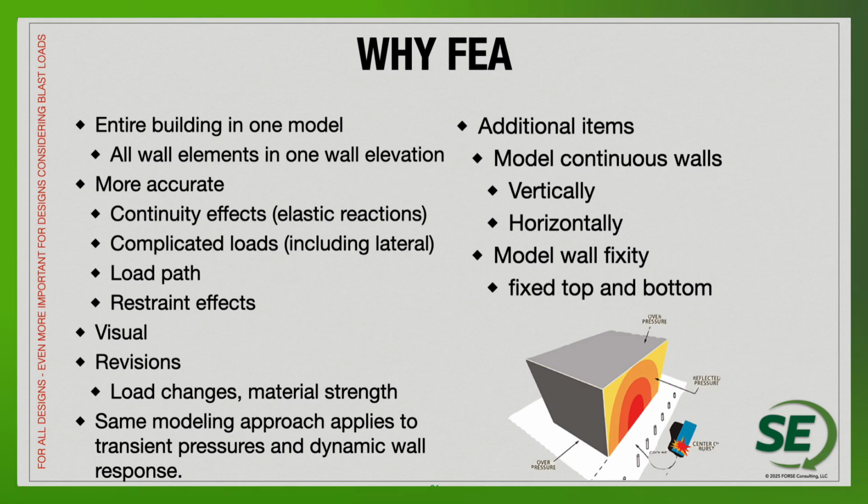And we can take that wall and make it longer, like we talked about, with minimal control joints and maybe a little bit more horizontal reinforcement. So using finite element analysis really does give us a lot of different abilities to look at masonry walls with a lot more complicated elements considered, which again make the wall much more resilient to some of those blast forces.